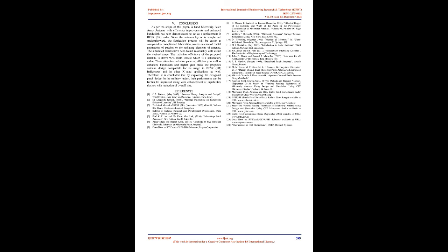The radiation pattern obtained at 10.2 GHz is presented below. It can be seen that the gain obtained at this frequency for the proposed patch array antenna is 32.24 dB. The radiation efficiency achieved in the proposed design is 90.29%, with losses, as compared to 88.22%, with losses, in case of the BFSR, SR antenna, which implies an improvement of 2.35%, considering realized gain.